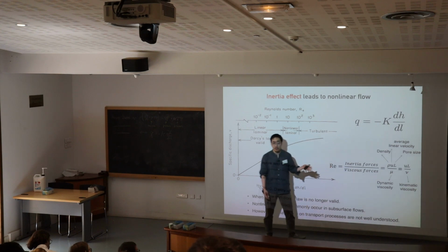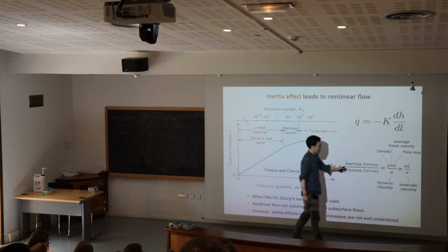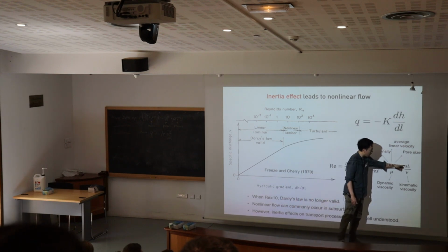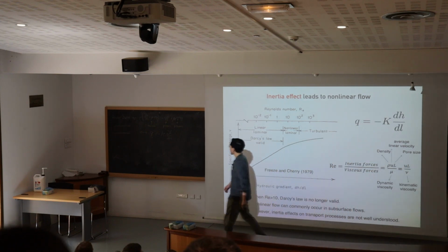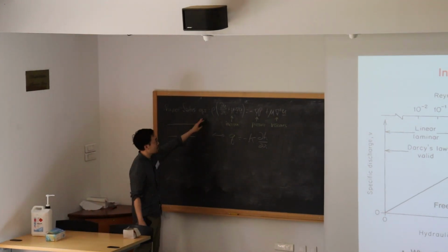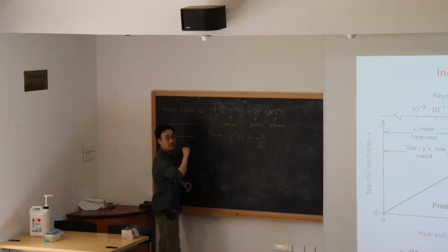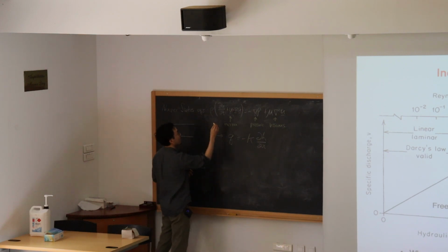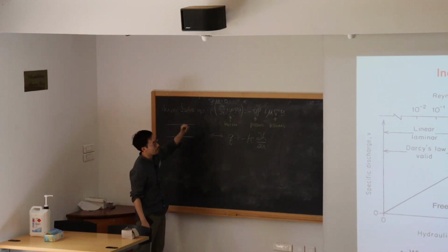So for Reynolds number, what we are trying to compare is inertia force over viscous force, right? And I'm sure you've seen this many times, which is velocity, length scale, and viscosity. But I think it's still informative to see where this is coming from. So we have this well-known Navier-Stokes equation, which is again the momentum balance equation that people have to solve for pore scale flow. And what is the other equation that we have to solve with Navier-Stokes for pore scale flow? Yeah, mass conservation. For the simple scenario, it is basically divergence of u equals 0.